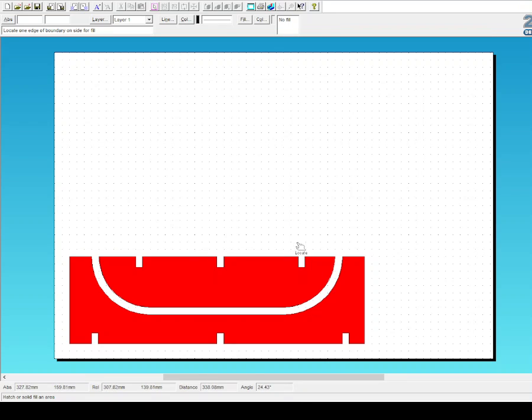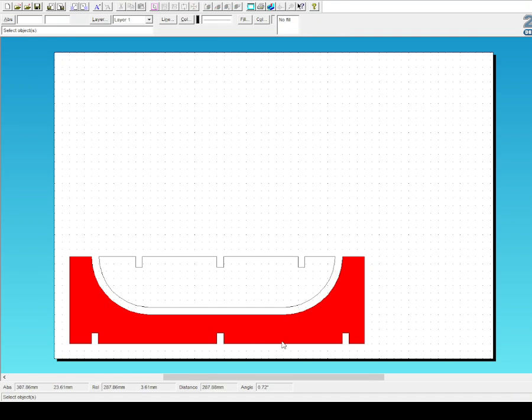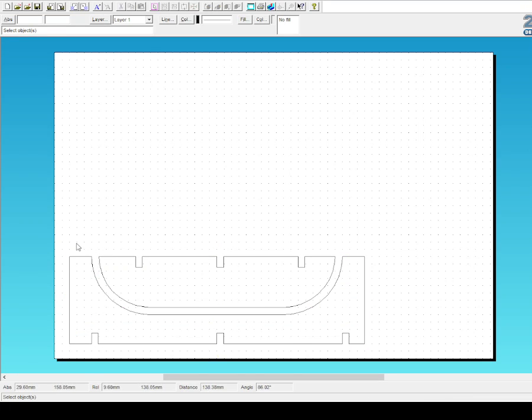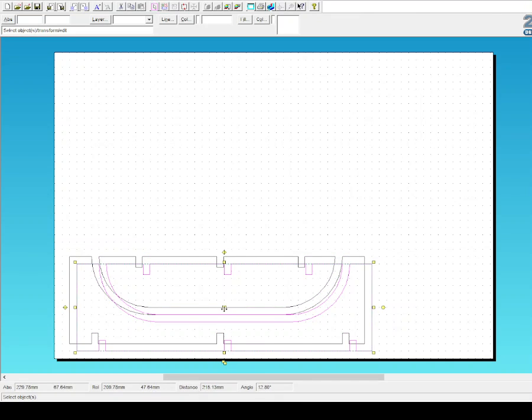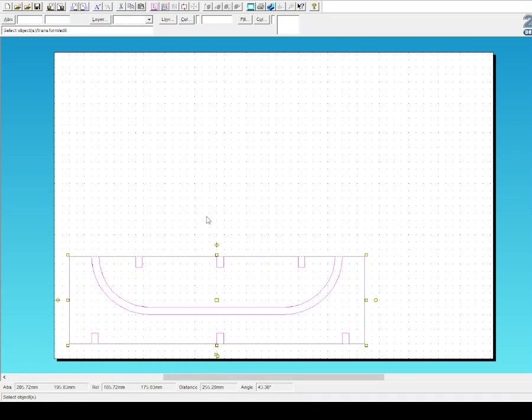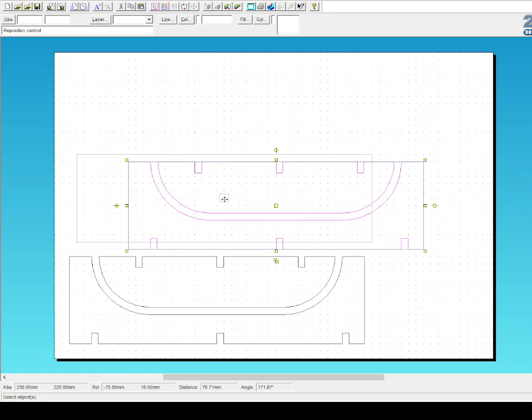If there was a gap, that shape would not fill. So I'm just going to select this area, delete, select that area, delete. Okay, I've checked it. At the end, I want you to fill this all in to show that you've done this check. I'm going to copy this shape, bring it up to here. Actually, I want to switch gridlock on for this. So I'm going to undo that last.